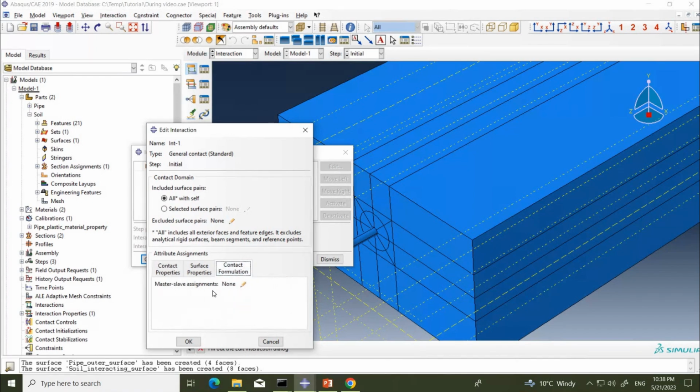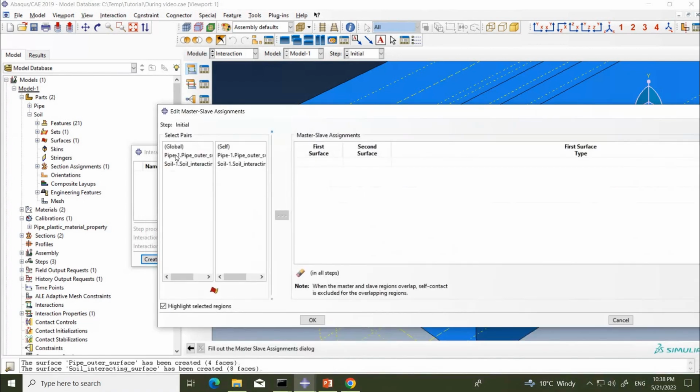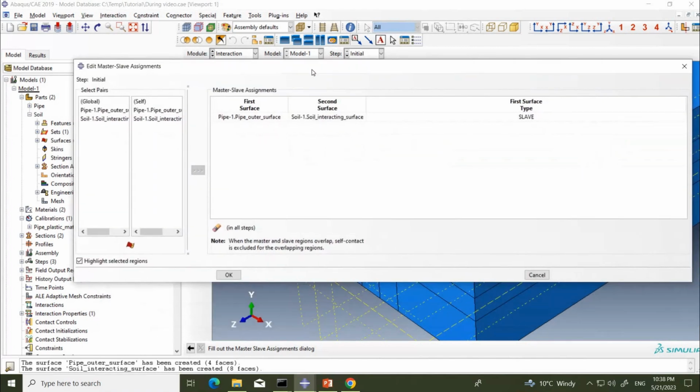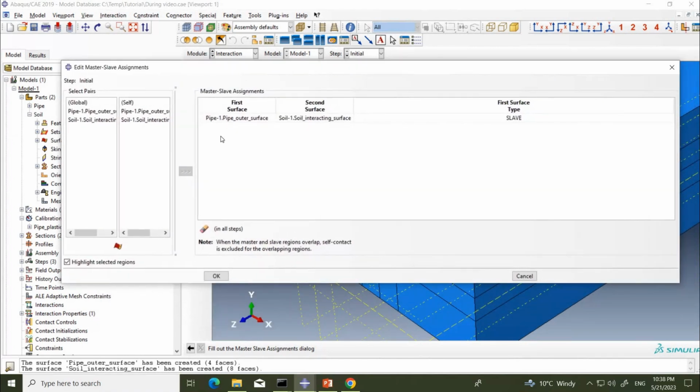Then contact formulation, master slave. In this problem, my pipe outer surface is the master and the soil is the slave surface. If you go through the documentation, you will learn in detail about what is master and what is slave. I'm not explaining this in the video.